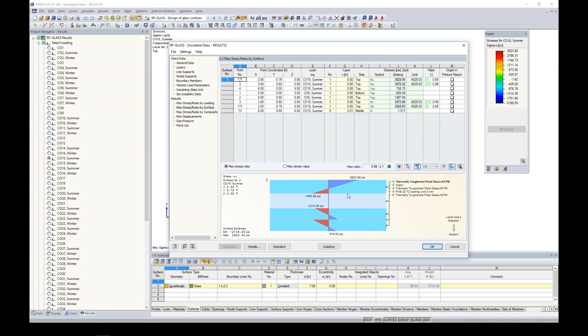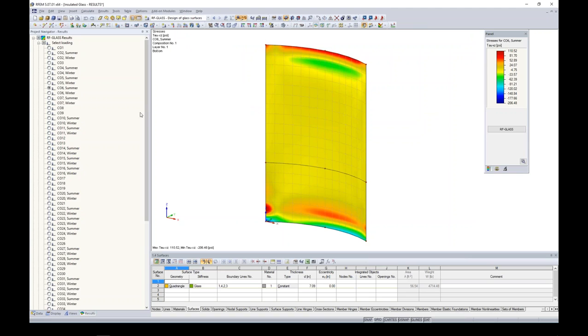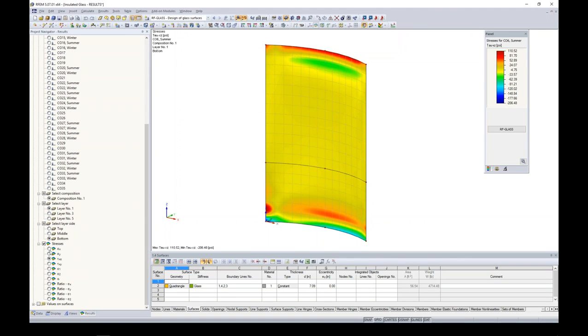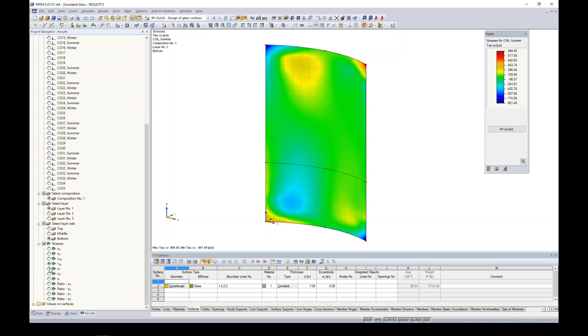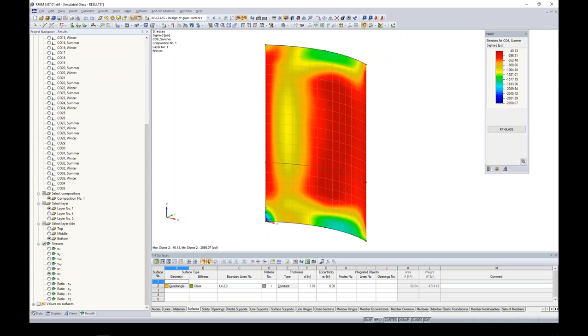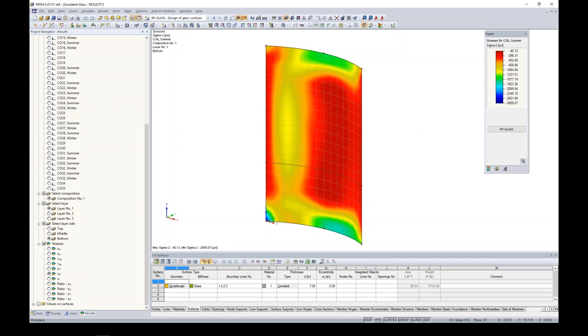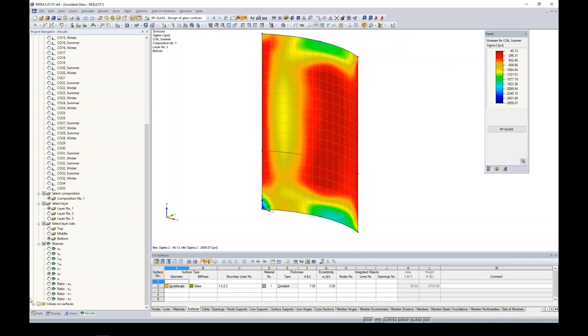So with this, we get the accurate shear coupling behavior based on the stiffnesses of our intermediate layers, which you can see here is modeled quite nicely with these diagrams that you can see for each layer. Jumping to our graphics, again, we have control over what stresses maybe we want to see graphically based on the contours. So nothing too different, essentially, than what we saw for the results from our plate theory.